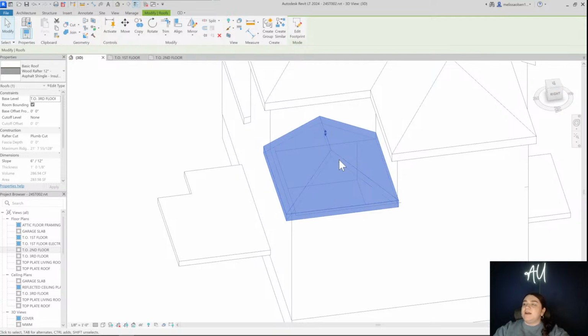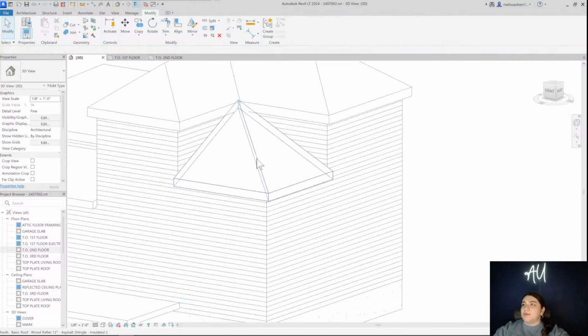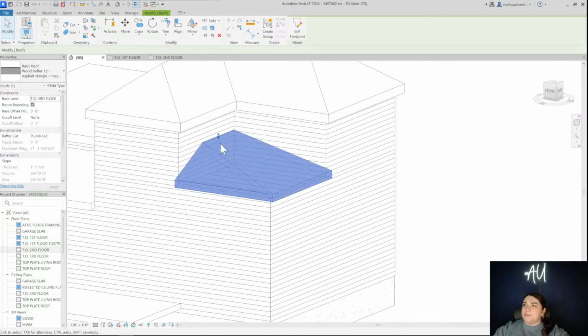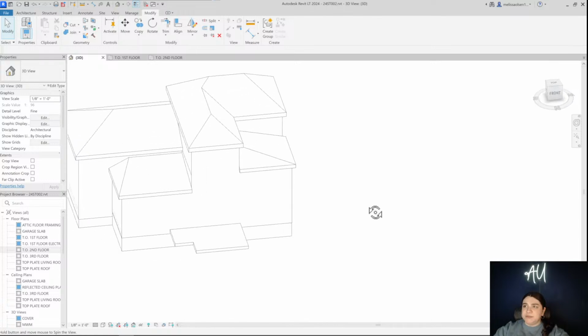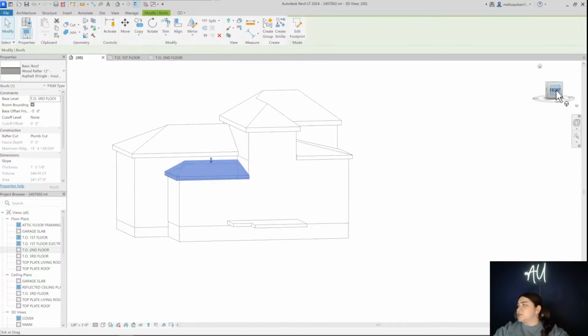We're going to do the same thing on this side because, again, we don't want water to be trapped in that area. We're going to unslope this up along the wall, and we're going to bring this down so that it looks a little bit more attractive. And we're just going to be keeping those two edges as a slope so that we can keep our hip style. This, I think, might need to proportionally come down more.